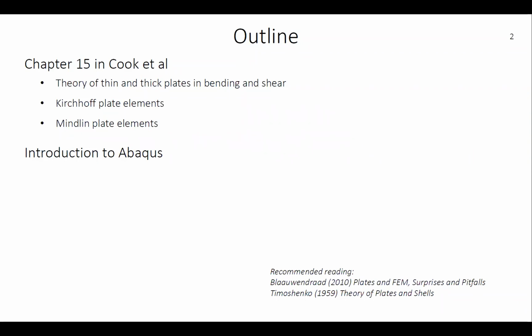So today I'm going to go through two fundamentally different plate elements, namely the Kirchhoff and the Mindlin plate elements, which basically are thin plate theory and thick plate theory. So they have their equivalents in beam theory, where you have Euler-Bernoulli and Timoshenko beam elements.